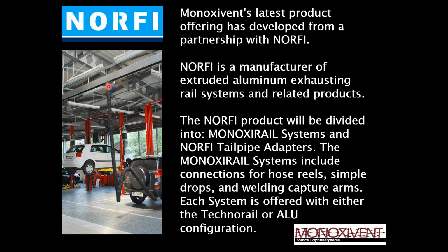If you think about it like this, this is the trolley, here's our rail, and here's an overhead drop. Let's say I have 8 bays, and this is your car dealership, and you've come to me and said, Mike, I need to get a source capture system involved. My first question to you would be, out of your 8 bays, how many engines do you ever have running at the same time? Right? So I have to always work around worst case scenarios. And it's never going to be 100%. There'll be a diversity factor of 30 or 40, whatever that number is. So let's say you go, Mike, I never run more than 3 vehicles at the same time.